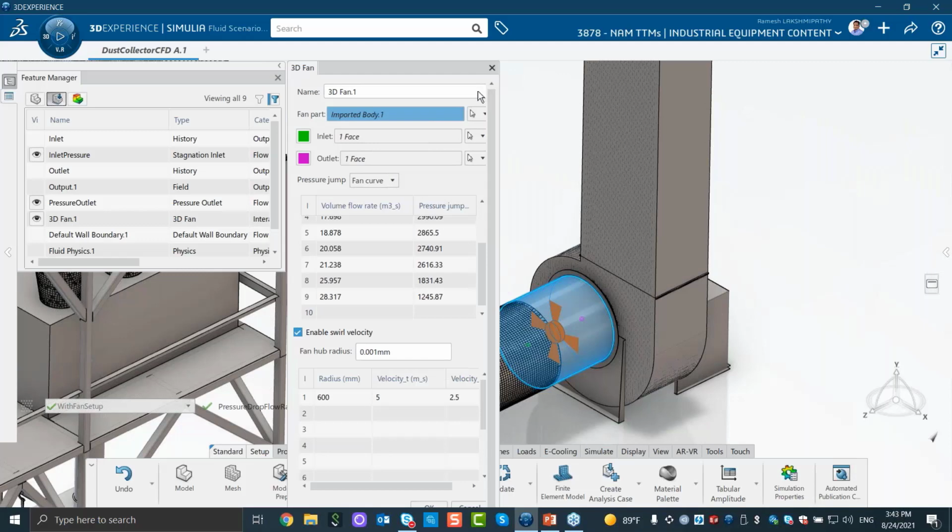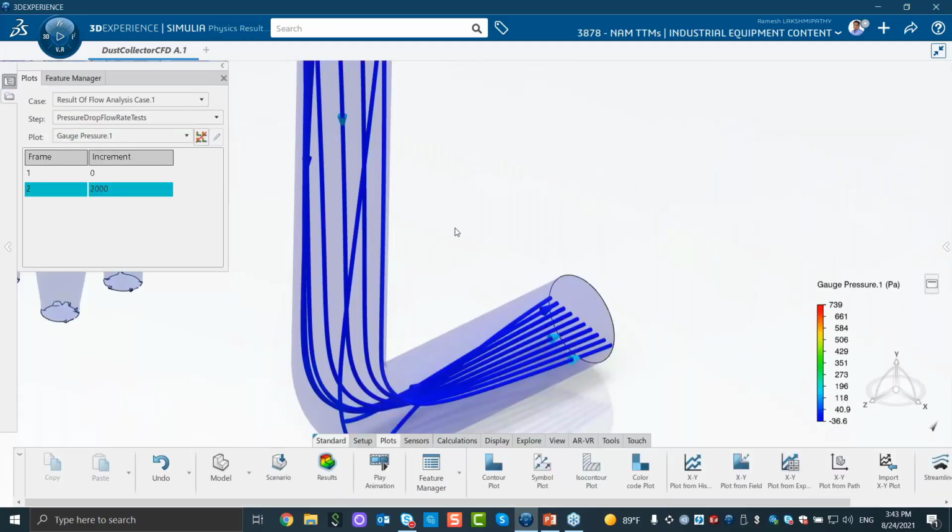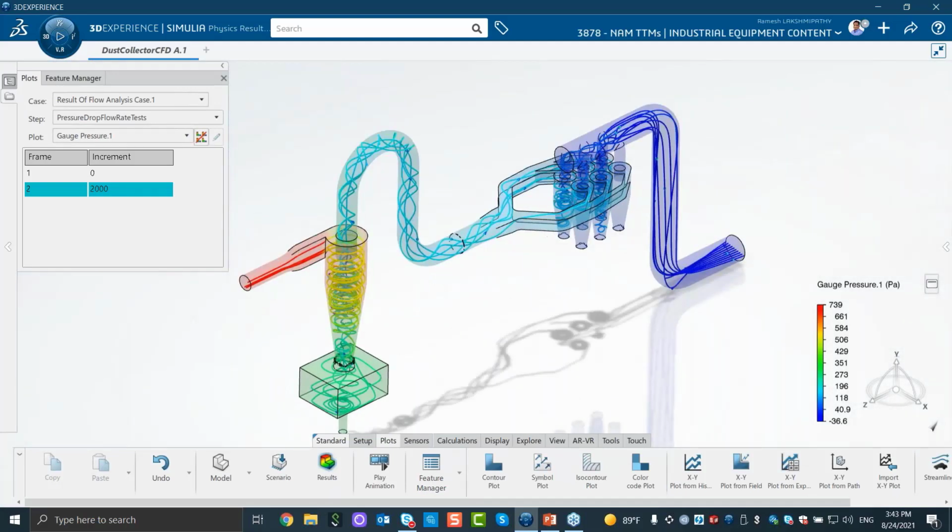Okay. So this is basically the workflow for this particular design, taking step by step, going from a baseline iteration, then figuring out what's the right fan to use, and then finally concluding which is the best fan, which will get the job done, and then including that fan in the process, and then looking at some key results. So here is what the pressure plot looks like. Sorry, not this one. So let's just switch to the results with the fan. So it might take a few seconds.